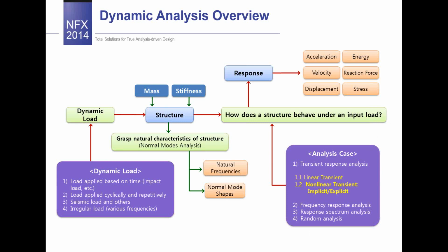We can choose between the transient response analysis, frequency response analysis, response spectrum, and random. And the most popular output is response as velocity, acceleration, and displacement characteristics.